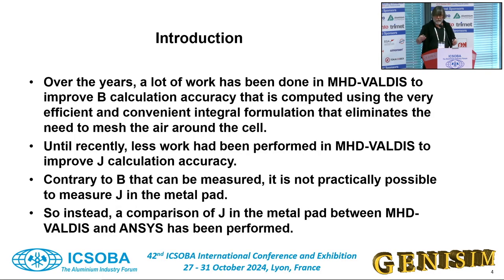Over the years, with MHD, we considered that it's mostly a magnetic field problem. So we designed the bus bar to have a nice Bz, so we have a stable cell. But the Lorentz force is J cross B, so the horizontal current has a significant impact on cell stability, and it needs to be accurately computed too.